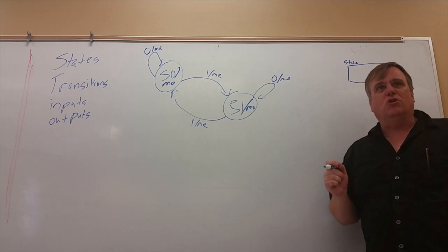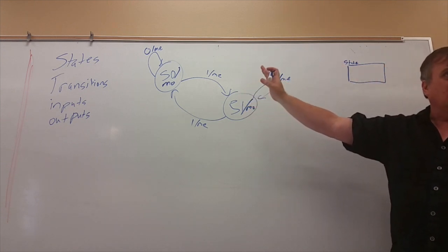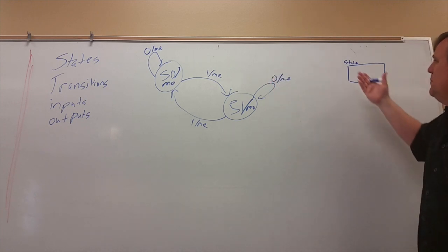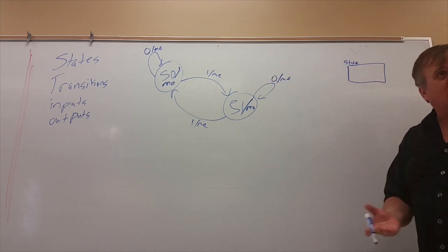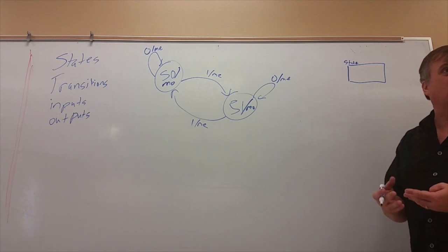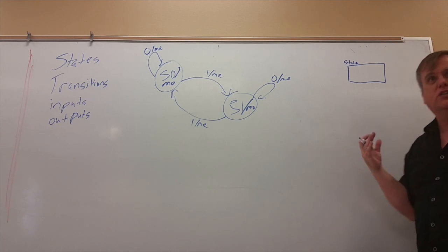Technically, an ASM chart just has these and the outputs and everything basically the same here. How does it handle inputs? How does it handle outputs? But we might also want to have some explicit calculations, and where do those calculations occur? The ASMD allows you to have variables in it, and you tell them how you process them and where you process them. So I'm just going to assume the ASMD because that's really more what you're going to do.